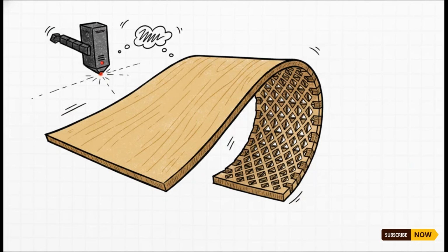But hey, kerf isn't just some annoying gap you have to compensate for. Clever engineers actually take advantage of it to create absolute magic. By cutting highly specific, repeating geometric patterns into a rigid sheet of wood or plastic, you vaporize just enough material to weaken the structure in a highly controlled way. The super thin webs of material left behind can actually undergo tension and torsion safely. This miraculously transforms brittle, rigid materials into flexible, compliant mechanisms.